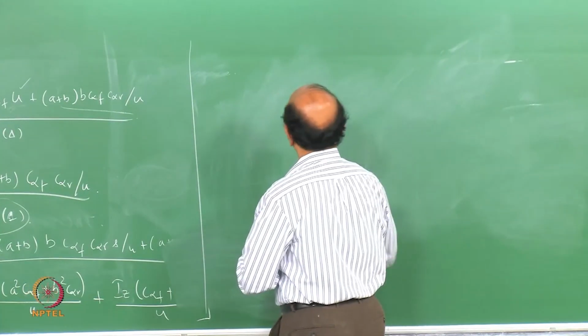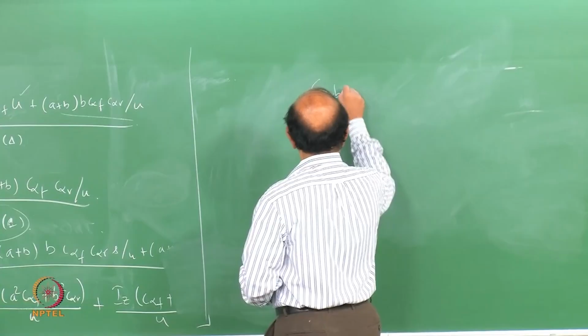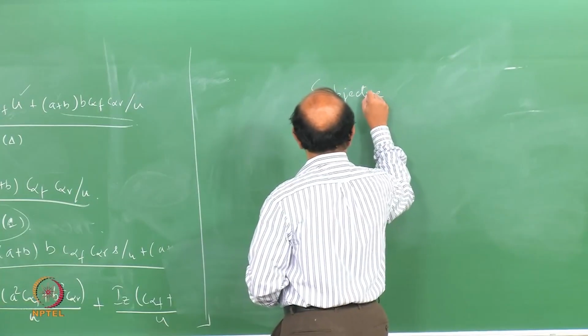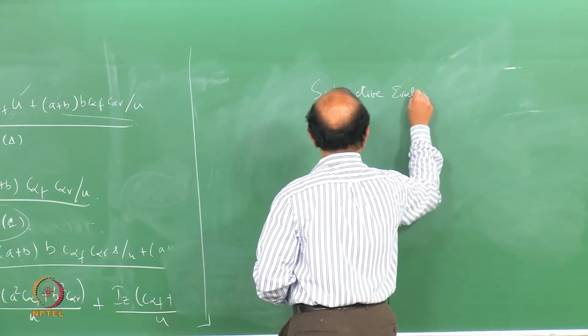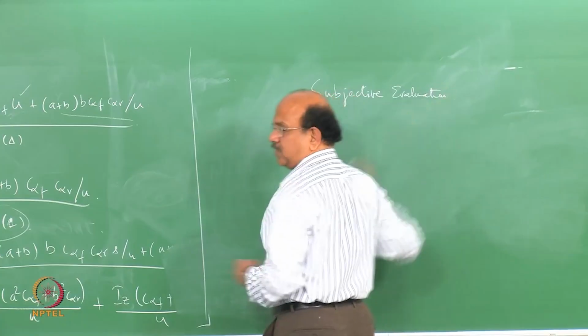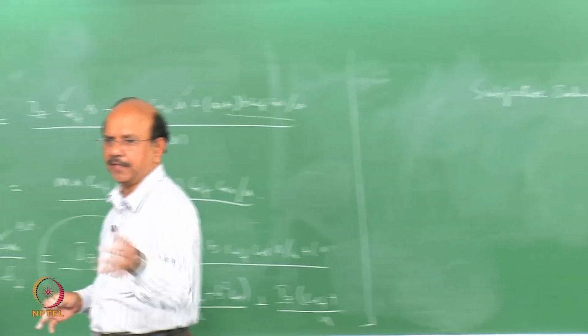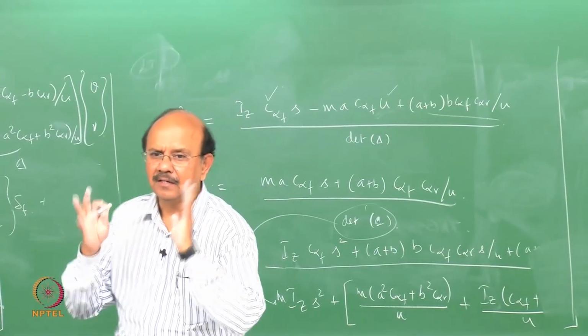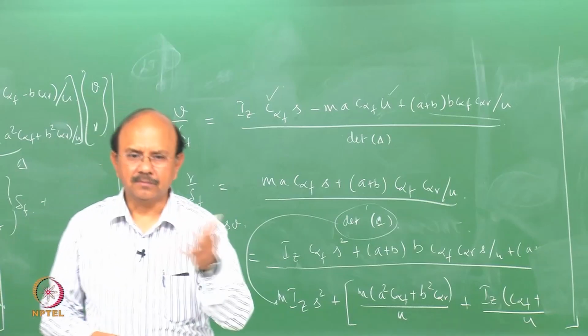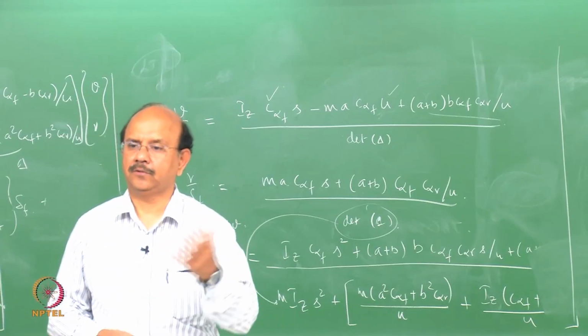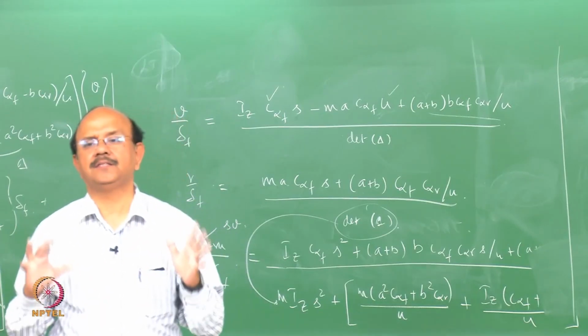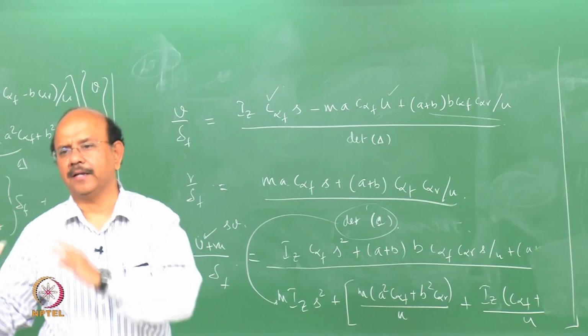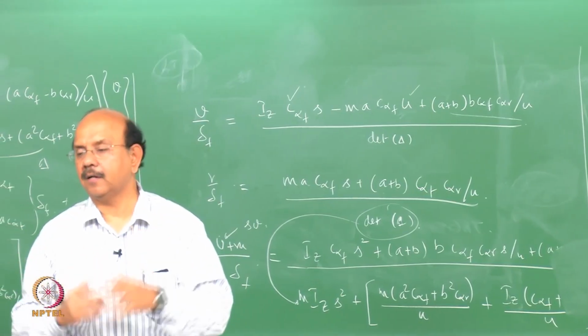This is just by driving the car. Drive the car, take a turn, take a double lane change. There are ISO standards for this. You do a slalom test, you do a pulse test, you do all those things and say, okay, I feel this car A is better than car B, and so on.